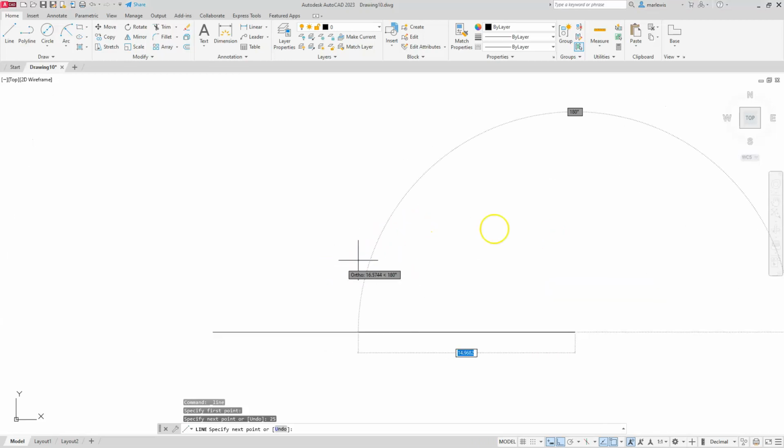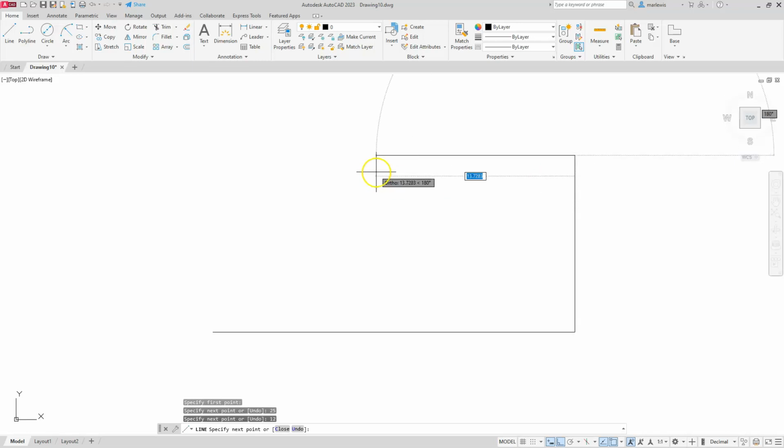So I made that line going 25 across. I'm going to go up a height of 12, back this direction at 25, and I accidentally put in a 2. And this is one of those common mistakes. Do not hit the escape button and get out of the command, but simply hit the undo and then come back, and now I can type in 25 and then C to close it.